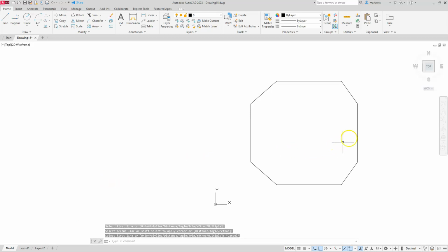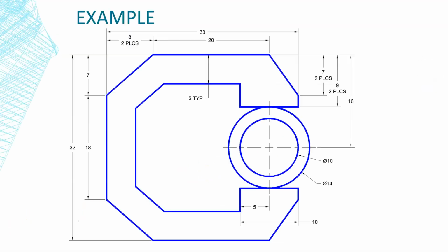Next thing I'm going to do is create a line from this midpoint going back a distance of 10. And that 10 I got is the actual dimension of the ledge. The ledge that I'm referring to is going to be these 2 ledges. So you can see that that dimension is 10, and this 5 just verifies and tells me that that circle, or these 2 circles, are centered right along that. So I need that 10, and that's where that number is coming from. I'm also going to use this diameter here in a second when I offset this line, so be prepared for that.